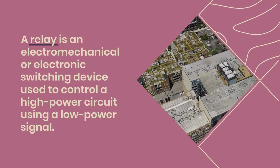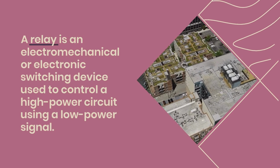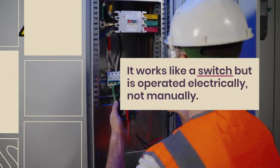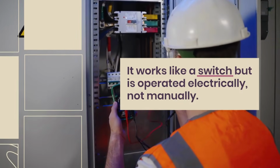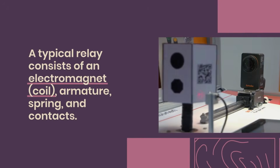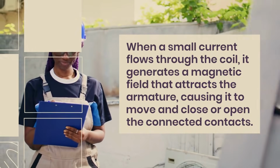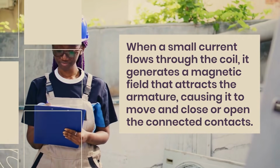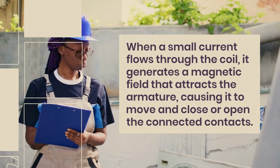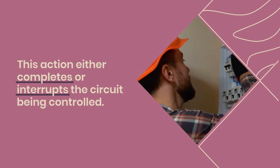14. What is a relay and how does it work? A relay is an electromechanical or electronic switching device used to control a high-power circuit using a low-power signal. It works like a switch but is operated electrically, not manually. A typical relay consists of an electromagnet, coil, armature, spring, and contacts. When a small current flows through the coil, it generates a magnetic field that attracts the armature, causing it to move and close or open the connected contacts. This action either completes or interrupts the circuit being controlled.